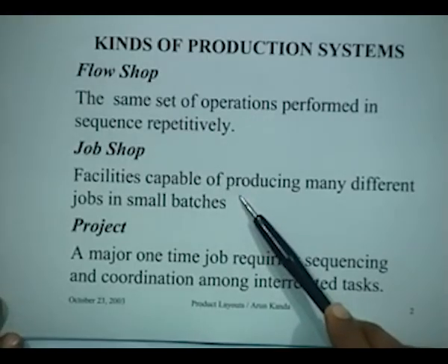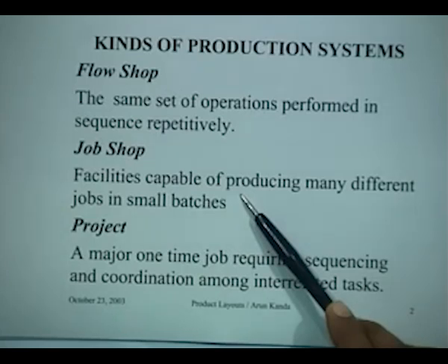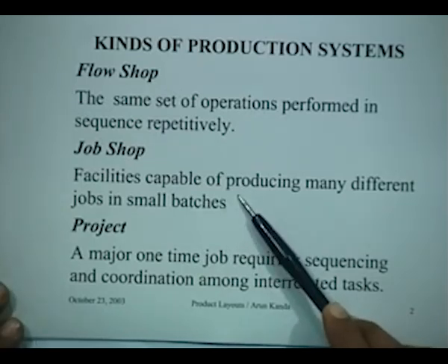So what really happens in the job shop is that the flow pattern is quite complicated, material handling costs are pretty high, and when you are designing layouts for such job shops, you are talking about the design of process layouts, which can accommodate the variety of products that you make. That is what we saw when we were dealing with both the systematic layout planning procedure of Muther and also the computerized layout planning packages which are there for handling such types of systems.